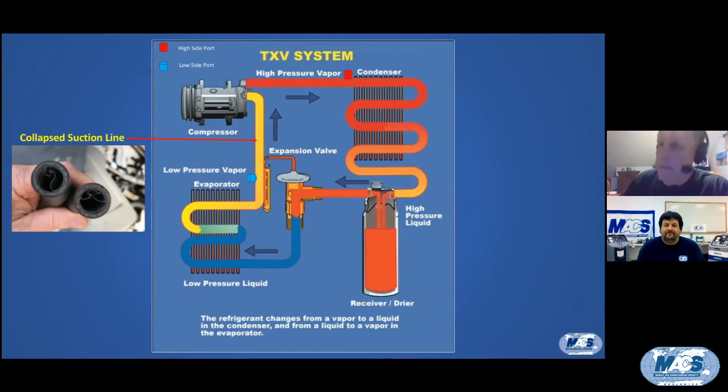So he's like, okay, he's listening to me at this point. So what do I need to do? What would you do if you're working on this vehicle itself? I said, I would do some temperature testing on it. Well, what do you mean? I said, well, you've only got 2 places in that system where you're supposed to have an abrupt temperature change. That's at the compressor, the inlet of the compressor versus the outlet, and at the expansion valve, which is one of the dividing points in the system. Anywhere else where you've got any sort of abrupt temperature change would tend to indicate a restriction. Now, through a condenser on a fixed displacement system like this, you'll typically get about a 20 to 50 degree temperature drop, but that's not an abrupt temperature drop.